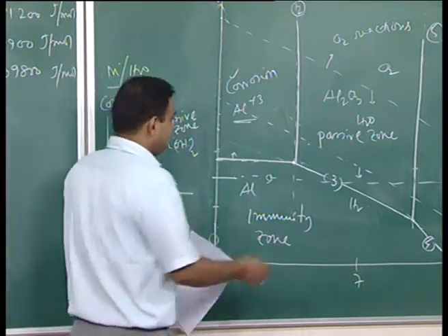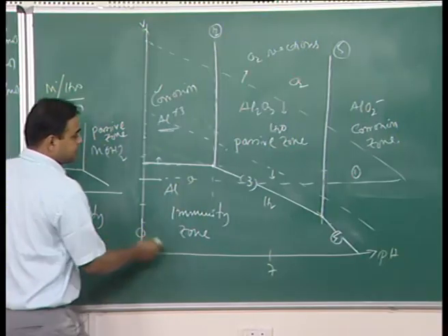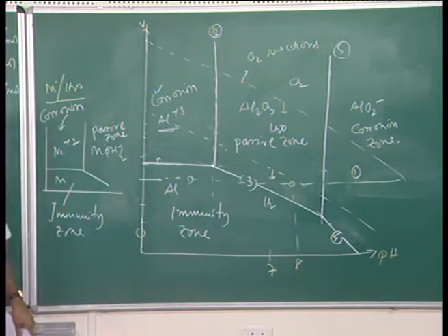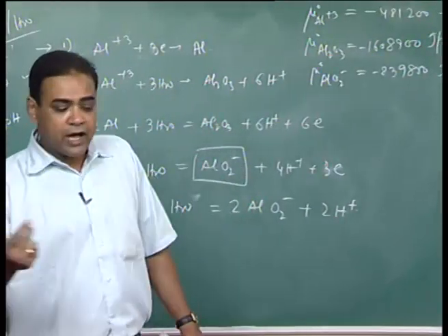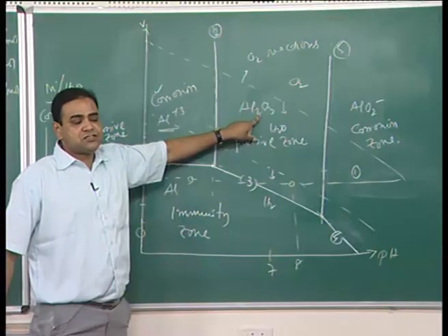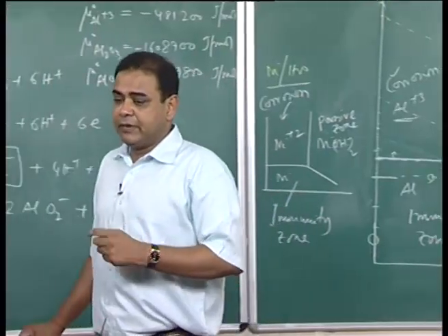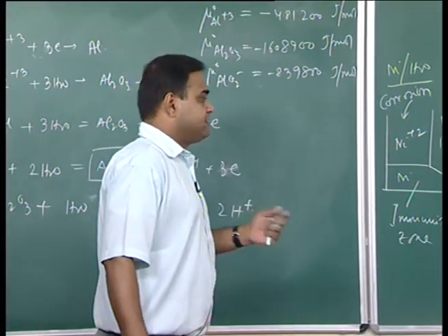Similarly, we have the common intention that if we increase the pH, let us say to pH 8, in a basic medium we always experience OH, metal hydroxide formation or metal oxide formation. Then we can say that this material is going to passivate if the pH is more than 7 or if it is a basic medium.